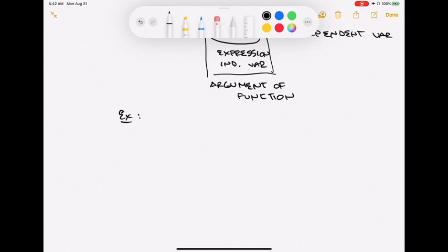I'm going to introduce the unit step function. We're going to call this u of t. U of t, by definition in this book, is 0 for t less than 0, and it's 1 for t greater than or equal to 0. This is a light switch function. At t equaling 0, we turn on the light, so the function becomes 1. Before that, it was 0.